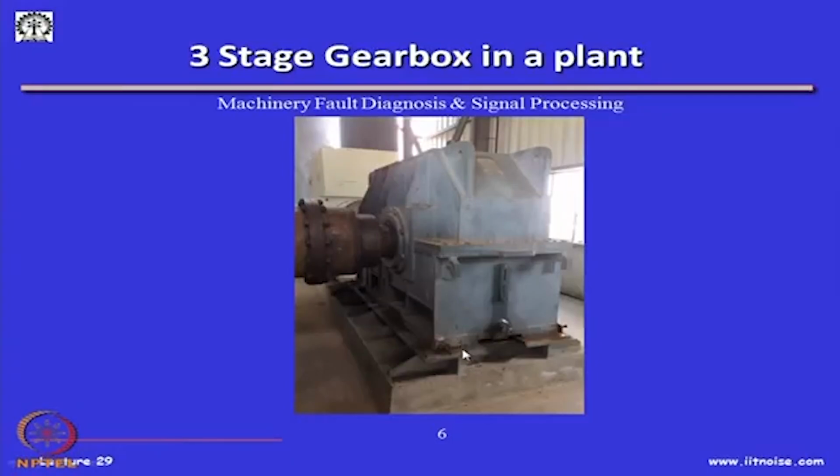Poor manufacturing of the gearbox housing, poor foundation, harsh environments, these all lead to the misalignment of the gearbox base, which in turn will increase the load, because there are heavy bearings here. There are usually rolling element bearings at this location, and these bearings will be responsible for unnecessary loads on the shaft here, and then there will be uneven wear.